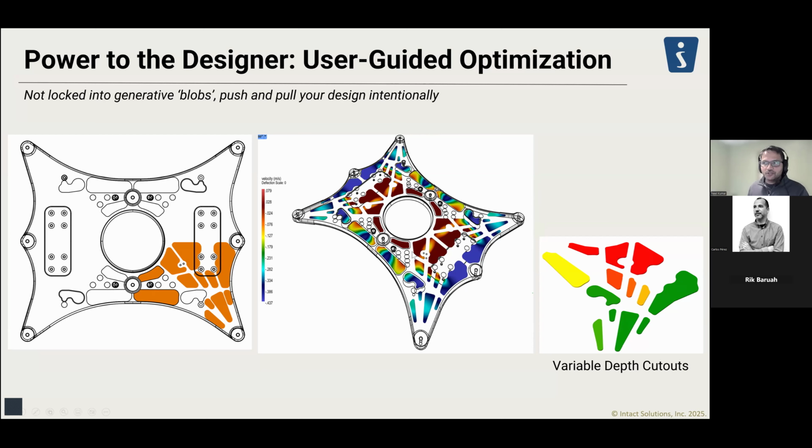So I don't want optimization. You just run LevelOpt with one iteration. It doesn't change the design, but it'll output the velocity feedback, which you see here. So we made the cutout domain the design domain, and the rest of it was part of the assembly. Now you see this velocity feedback on the cutout regions. The more red is telling you not to remove material, and the blues and the greens are telling you that you can remove material. But you can see it's a very organic, smoothly varying field. But I don't want to remove material organically. I want to make uniform cutouts for each profile.